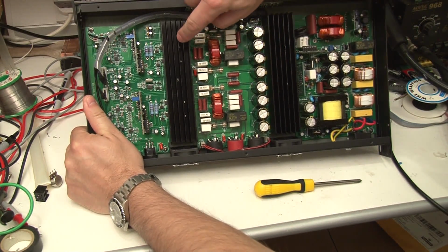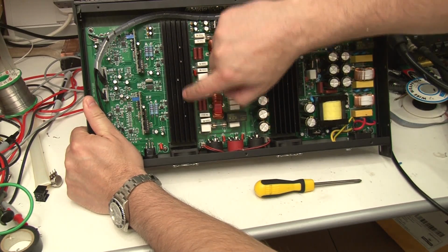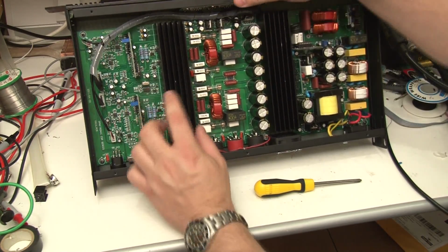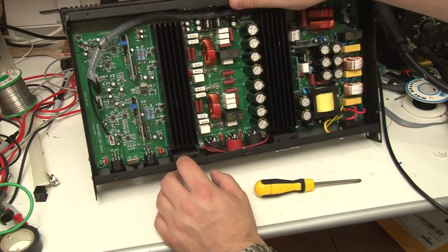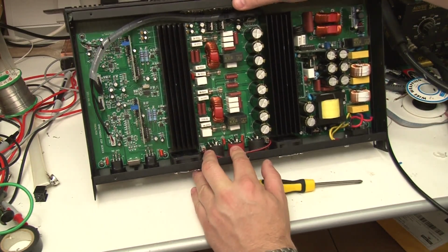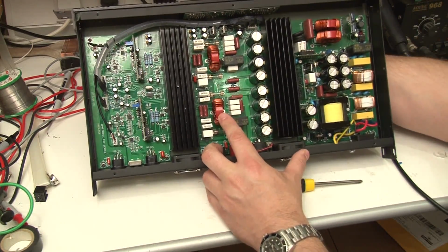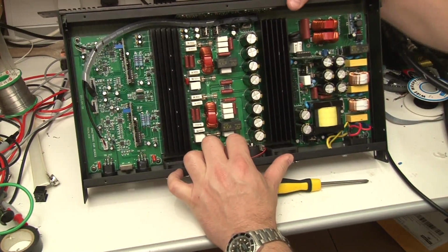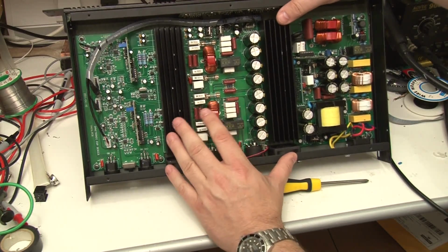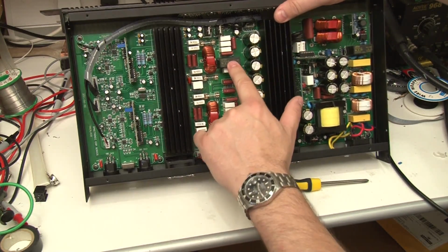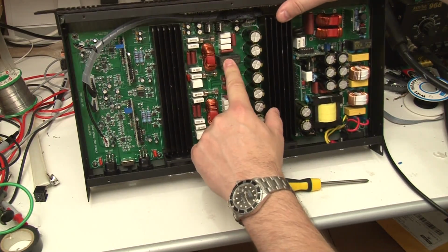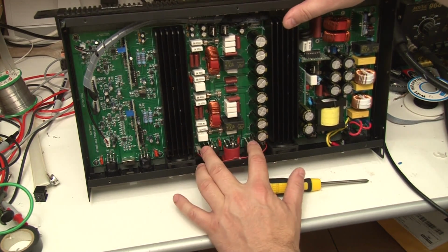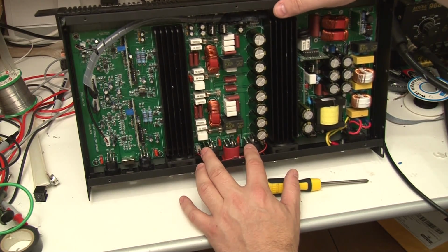There you go. You can see that they're either switching FETs or they're actually an IC, and it actually could be either. They could be a hybrid integrated circuit for each channel. And then this is the output filtering. Fairly substantial inductors, lots of ceramic resistors and capacitors here, making up the snubbing output. There's a couple of relays here as well. So this is the output protection, which I suspect is built back in here, and also this will isolate the speaker outputs once you turn the power on and off to stop it clicking or popping.